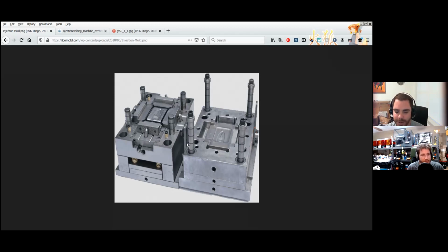Okay. And then on the male side, you'll notice in the middle there's a gap. Yeah, there's a gap and there are some springs there. Right, and that allows the various ejector pins that pop the part out to actuate. So, I think we can actually see them. Looks like there's one toward the bottom, left, right, and top, right?